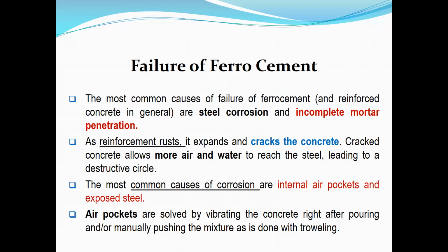You know, in case of ferrocement, the wire meshes are very closely spaced. Then you have to place the mortar inside. So if the mortar cannot penetrate inside the wire mesh, that incomplete mortar penetration may cause failure. And then a lot of reinforcements in the form of steel wires, wire mesh, or welded rods are used. So these will be subjected to corrosion, rust.